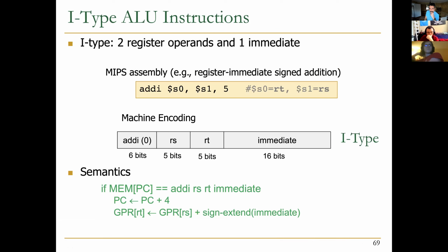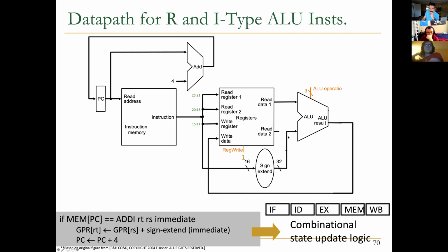But here, sometimes we need to wire this, sometimes we need to wire this. And this is an option for how we can put them together. So depending on the type of instruction, the right data goes to the right place. This is again about data movement, right? We are constructing data paths, and as we add more instructions, we don't want to cut part of the data path that was needed for other types of instruction. This is the thing that I'm discussing, right? So as we add the I type, we don't want to mess with the R type. We still want this macro architecture to implement R type.